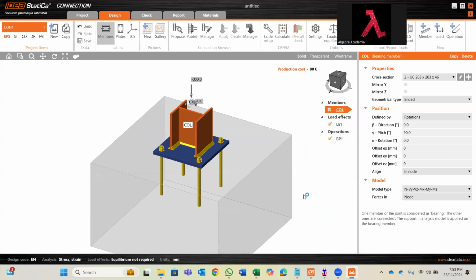I'll come one by one. I'm not going to be in a hurry, jumping from one to another. Once we fix the section sizes, I'll go to the base plate. Without changing the base plate dimension, don't jump into the bolt diameter, because it doesn't make sense. You need to fix the base plate dimension first. How do you fix the base plate dimension? We have discussed this several times in the classes, but however, I wanted to show you.